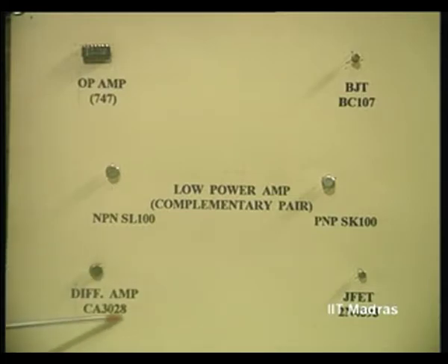Then we have another unit which we had discussed in the class, the differential amplifier. This comprises a pair of matched transistors with a current source, with all the biasing incorporated in it. Collector loads are kept open. So, the two collectors are open collectors, so that you can connect whatever you want. CA3028 is a very useful differential amplifier used for video as well as wideband and high frequency IF and RF applications. This also we will see later, how this differential amplifier can be used.